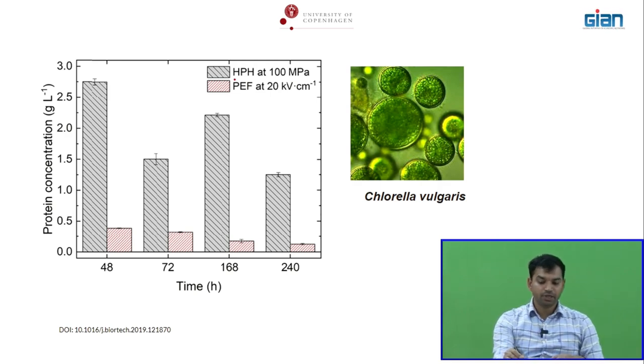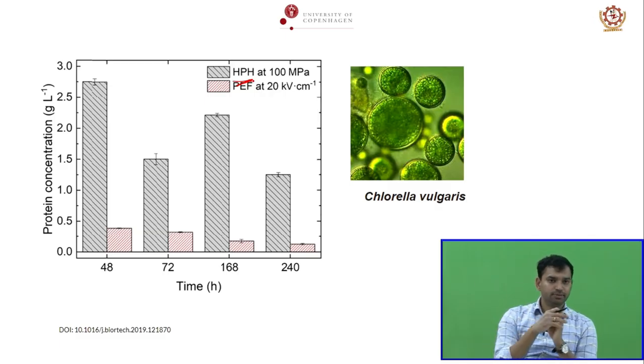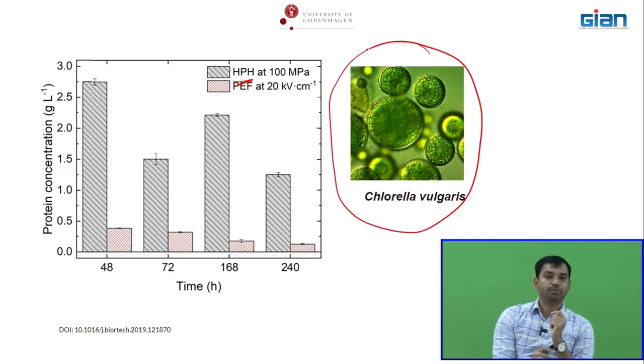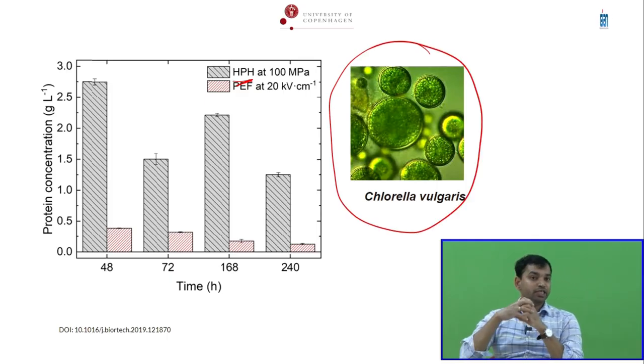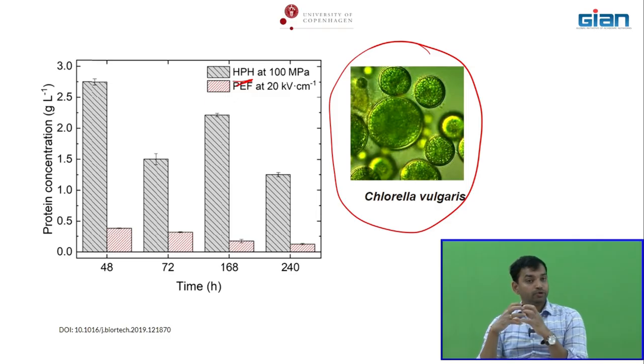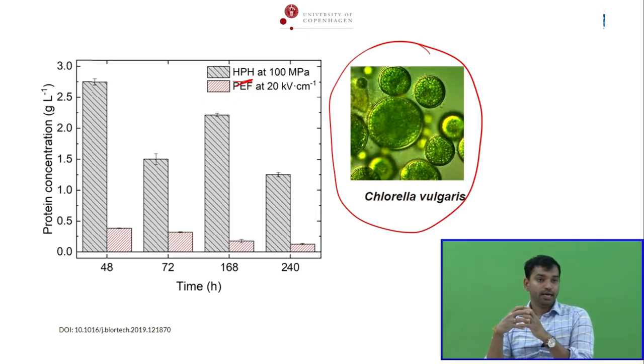So when compared to high pressure homogenization, you know the technique they use, the high pressure homogenization is a normal technique used to break down the cells. It's not that efficient. So it can be used, but PEF is not a really efficient technique, especially to extract proteins from cells that has very strong cell wall. Please note that cell wall cannot be damaged by PEF. Cell membranes can be damaged by PEF. To damage the cell wall, you have to apply extremely high electric voltage, and that we call high voltage discharge. It's another technique, but it's not very energy efficient.